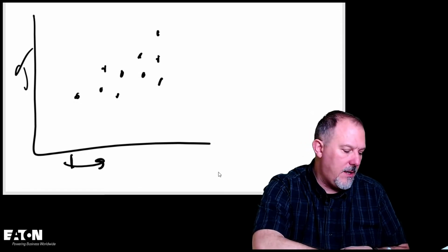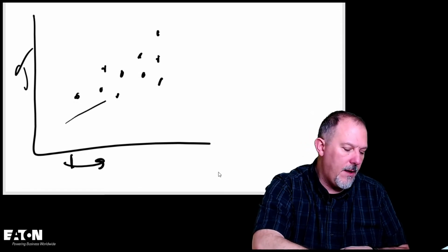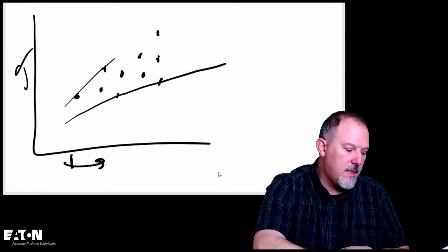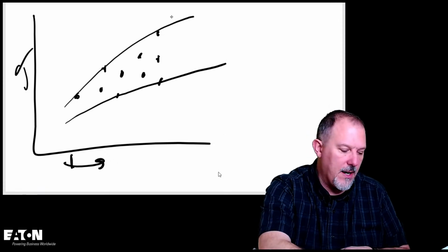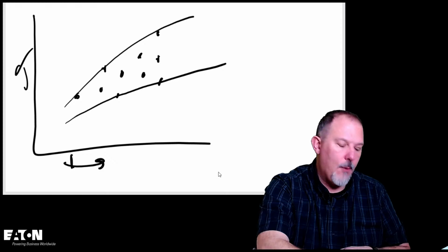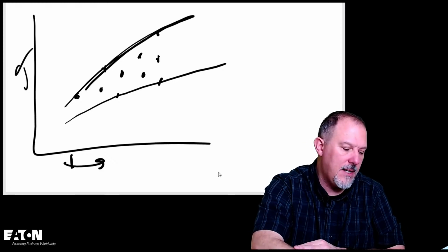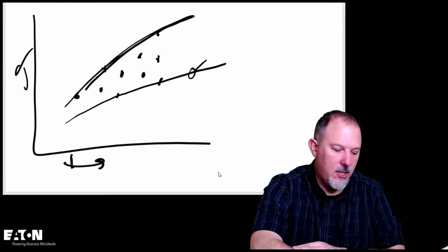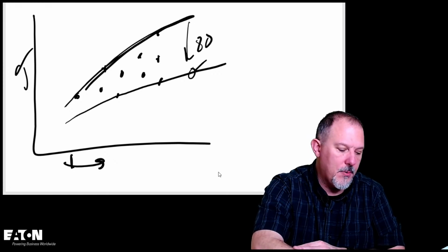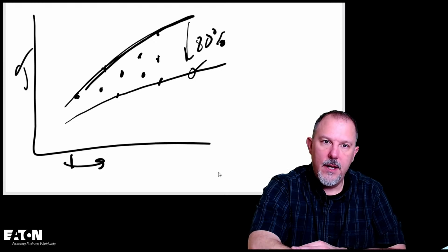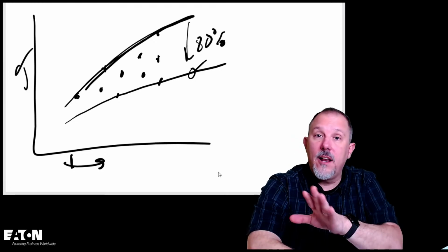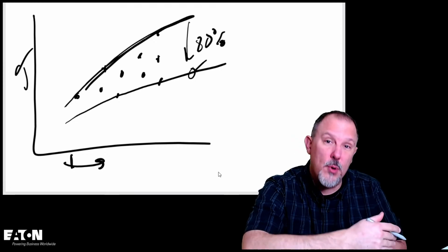And you may say this is the minimum arcing current and this is the maximum arcing current. So you've got a band. And what he did before was he calculated this and said that the minimum arcing current is 80%. And that was a lot of error. So your minimum arcing currents were pretty low.